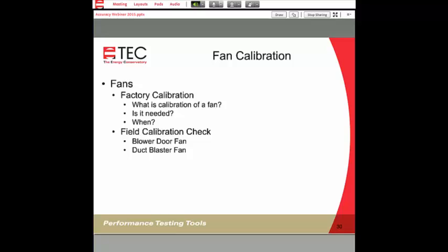You can take a piece of hose and connect from the input to the reference side, and when that's working properly, that should be reading 0. And then you want to check from channel A to channel B, just a single piece of tubing across that, and those should be reading the same value. When they read the same value, you can see that as a general check that both sensors are going to work.